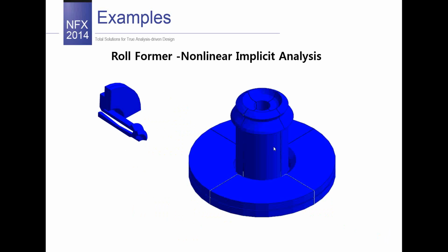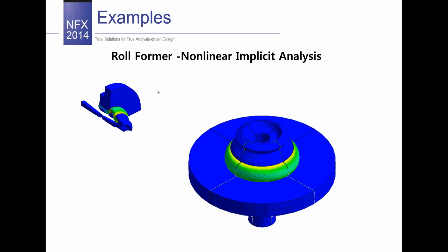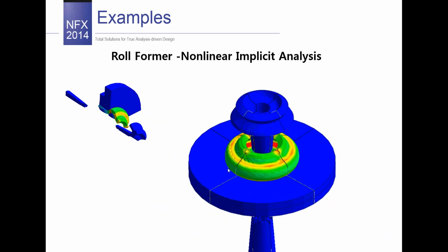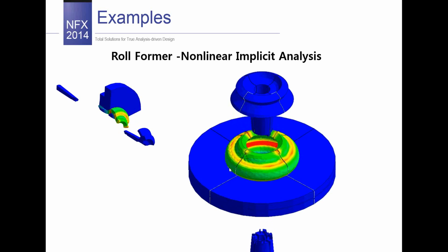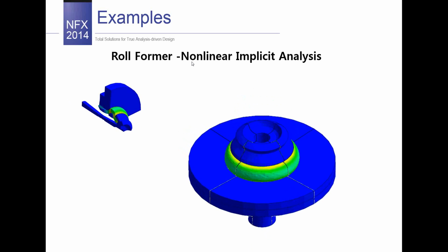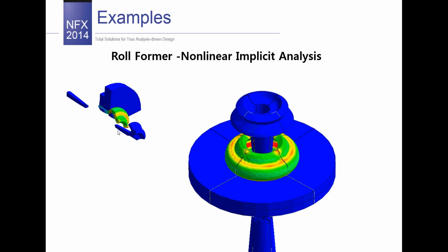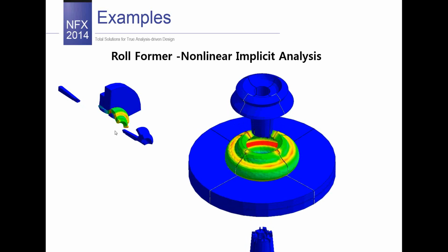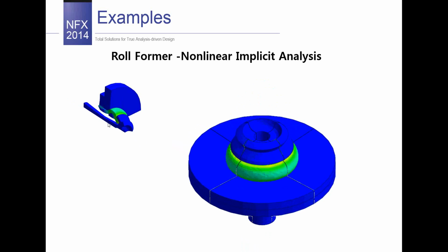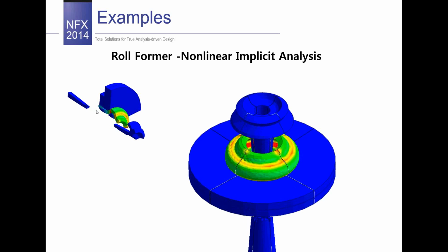And now I will show you another example, and this refers to the riveting process, and this example was made using the explicit method. Sorry for the mistake on the slide. This should be a nonlinear explicit. And in this example, as you see, we also used our new feature, which is called the element dilation feature, and that's why this part is broken.